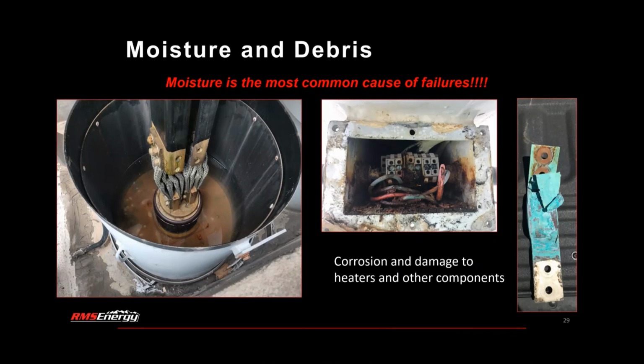So it's important to note when you're doing periodic maintenance or an inspection, or even just testing and maintenance on adjacent equipment, if it's noticeable that there's standing water, condensation, or even just a noticeable difference in humidity on the internal of the bus duct, you should take that as an opportunity to investigate where the source is and see if that can be mitigated.